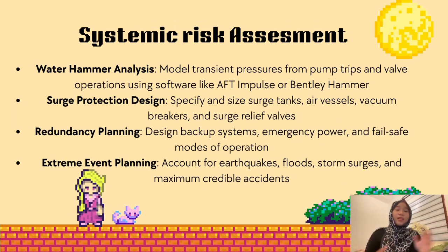Second key point under the engineering responsibilities is systemic risk assessment. So these are the key points that I have found, which is water hammer analysis for the first one, which is moderate transient pressure from pump trips and valve operation using software like AFT Impulse or Bentley Hammer. For the second point is surge protection design, specify and size surge tanks, air vessels, vacuum breakers, and surge relief valve. So for the third key point, which is redundancy planning, where design backup system, emergency power, and fail-safe modes of operation.